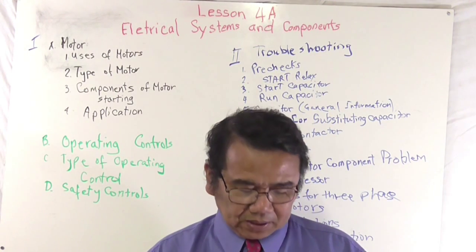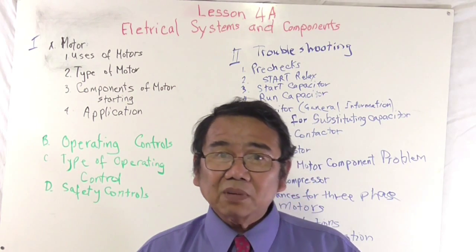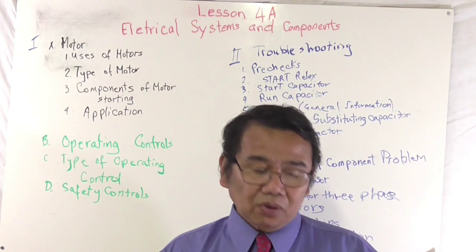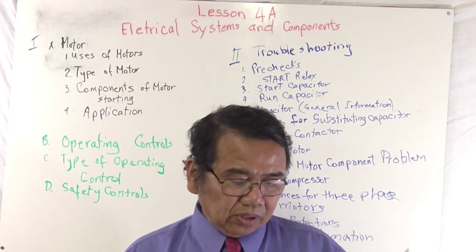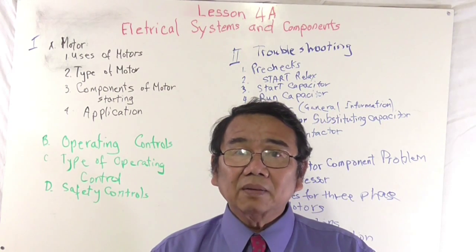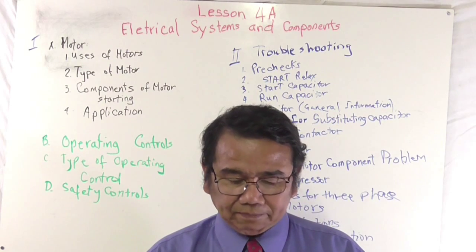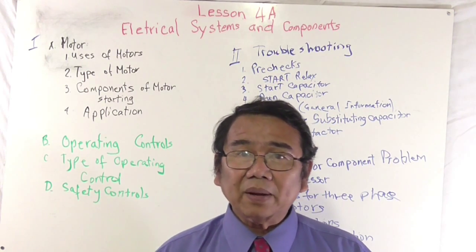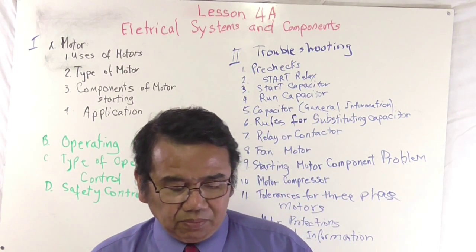And then the run capacitor. Run capacitor, open circuit, same as start capacitor. And then you have a wrong size, same as start capacitor. And then you have a burnout: voltage is high. And then we're going to discuss the general information about capacitors.